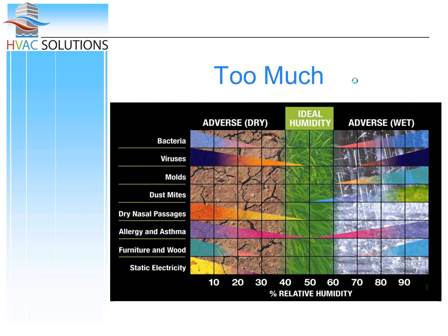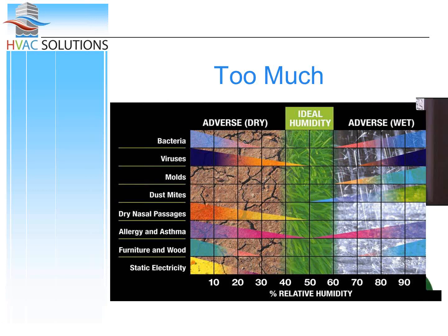Or if you leave wet towels in the carpet or on the bed, that changes things. So you could have less than 50% in the air and still have dust mites if you have higher relative humidity in certain spaces. I'll say that from experience. That one took forever to figure out. Some other reasons you might want a dehumidifier: keep condensation off the windows and keep wood floors from buckling.